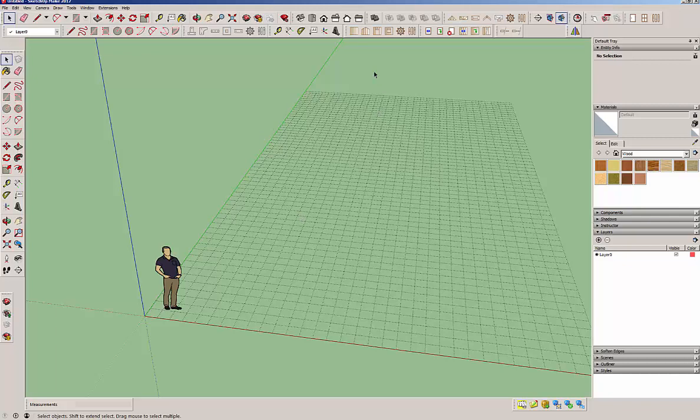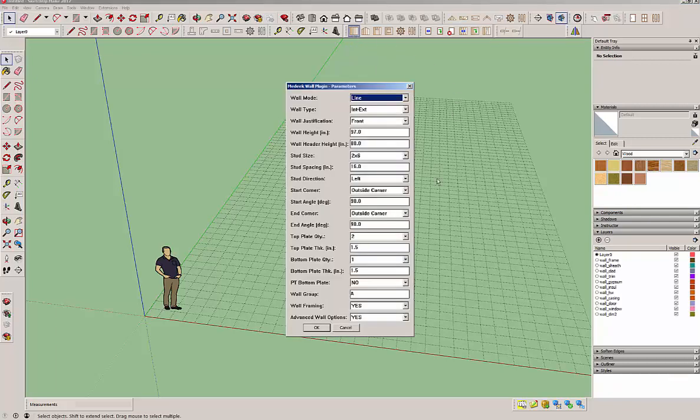So first of all, with the wall plugin, I've been working on adding in the Polyline and the auto corner configuration tool. So what we're going to do is instead of using the line mode, we're going to go to the Polyline mode. And I know you can still use the line mode and it'll do the same thing. But the Polyline mode is kind of nice because it lets you keep drawing walls as you progress.